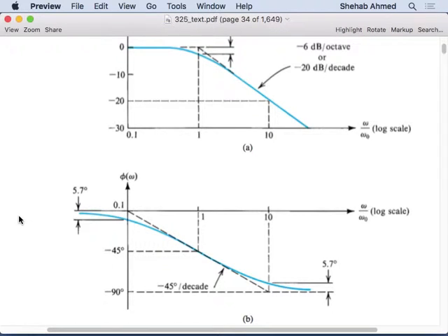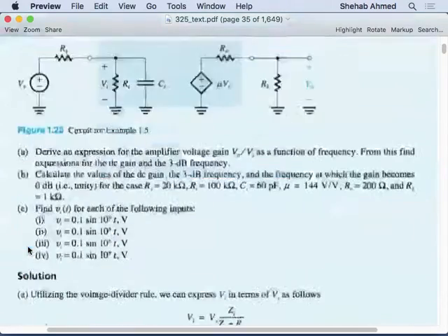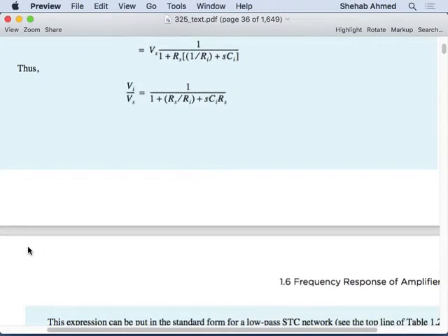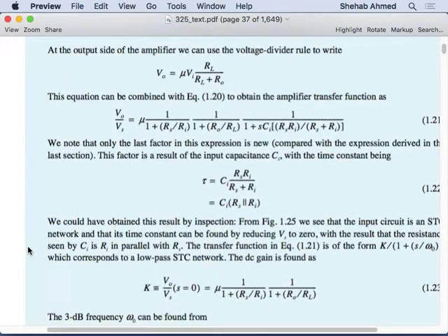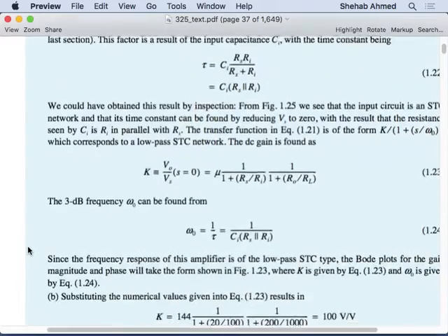I can do it this way or that way. And the textbook says that. You can do it this way or that way. But that's why these curves are nice. If you understand these curves and what they mean, then khalas, you don't need to substitute numbers and stuff like that. And you don't need to derive these transfer functions because you go to the capacitor, see what the parallel resistances are across the capacitor, and you have your time constant. You have your time constant, which means you have omega naught. You open up your capacitors and find your DC gain, then you have your K. That's it, you're done. You don't need to include impedances and complex numbers and stuff like that. It's easy, but you have to understand.